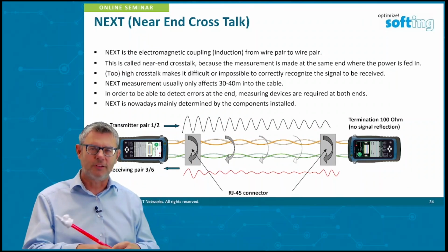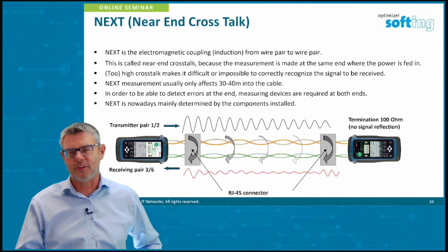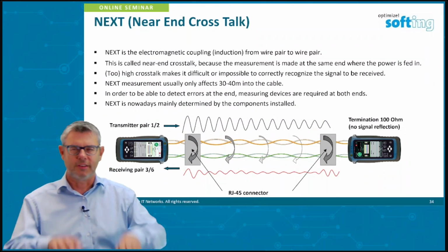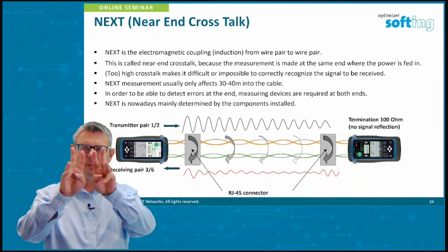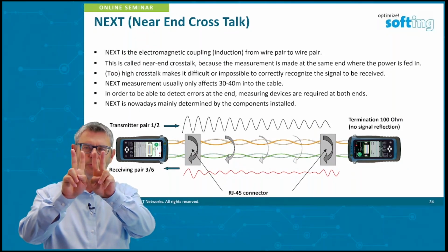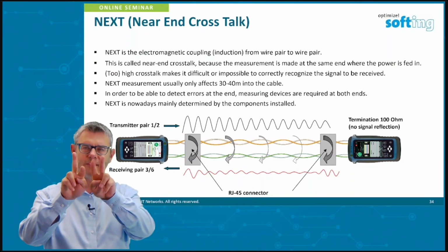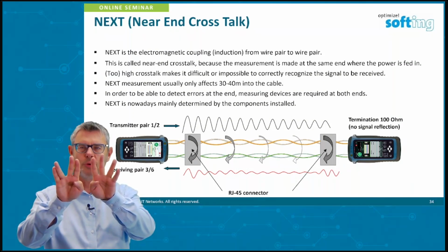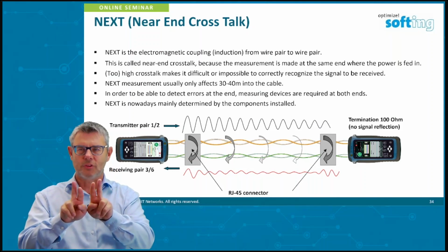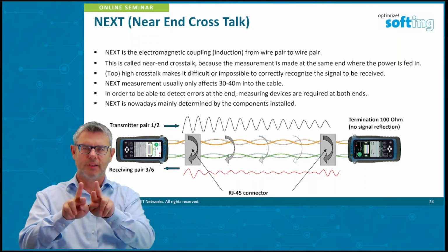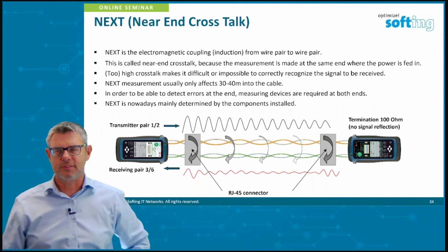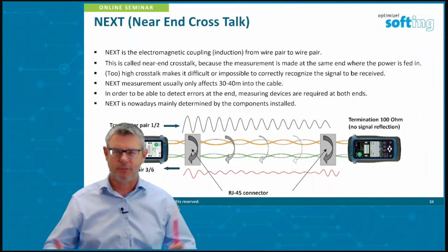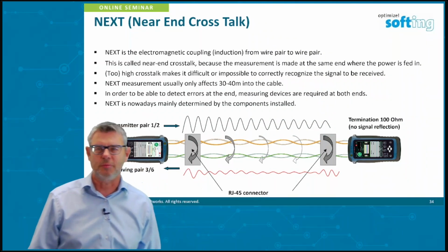And at the end of the connector, we have this funny situation that we have these 8 lines, and what we are doing is we are crossing 3, 6, and 4, 5 in the middle. So it's not as we would like to have these 4 pairs this way, but unfortunately one pair is enclosing the other ones, and this is RF. For our parameters, it's absolutely a nightmare.